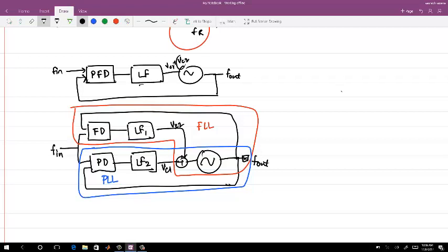Whereas I can separately control the thing. A quick example would be a ring oscillator. I control the current source of the ring oscillator to control the frequency. That's the easiest part. Now if I use a PFD which governs the whole frequency and phase of this oscillator, and let's say this is a 1 milliampere current, I should be able to vary this 1 milliampere current completely.